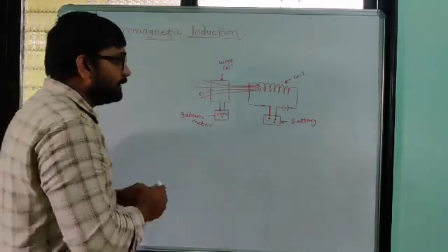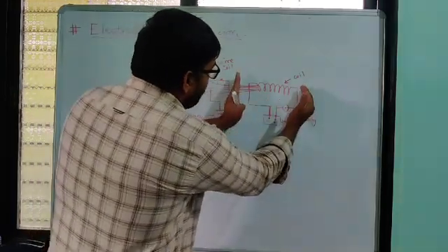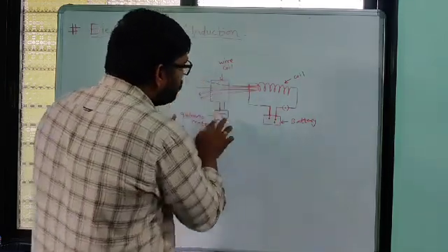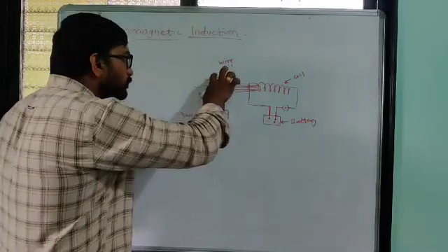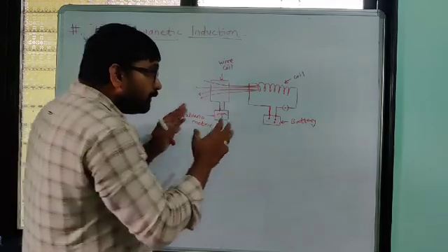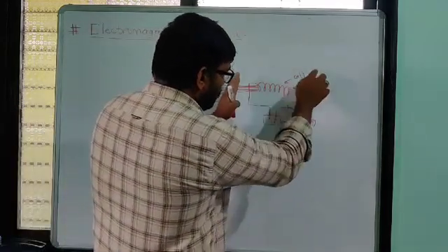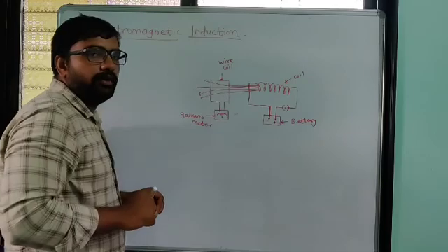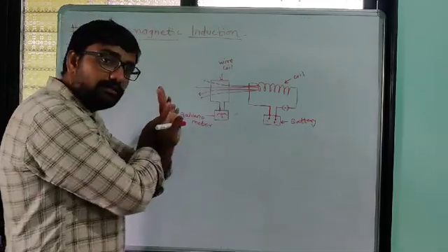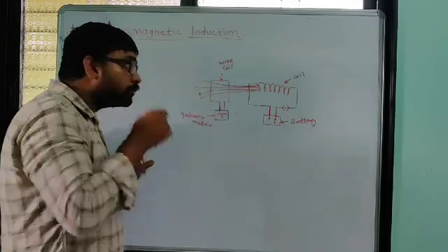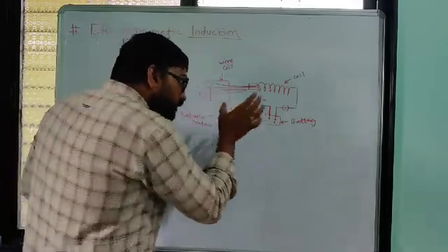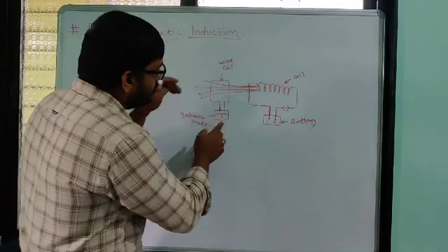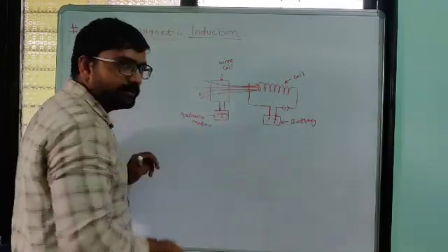So we can say that as we turn on the electric current here, due to that current, this coil here, actually we do not connect any electrical supply, this is only an electric coil. Okay, so due to the current passing in this coil, electricity is generated in this second coil. Actually, no electric connection is given to this coil. Due to the passing of electric current in this coil, electric current automatically passes through this second coil, because we see some deflection in this galvanometer.